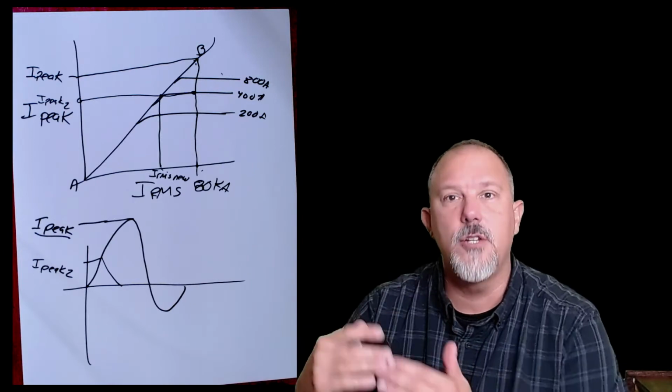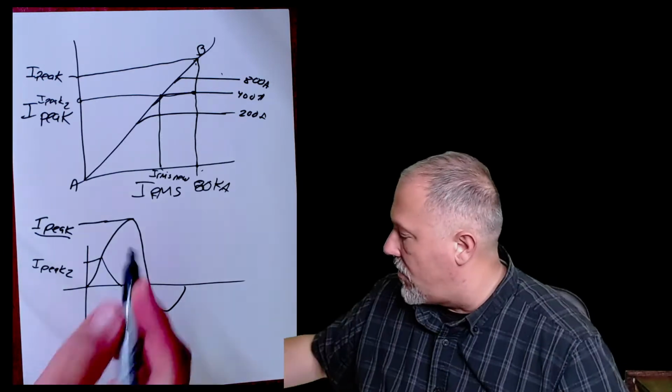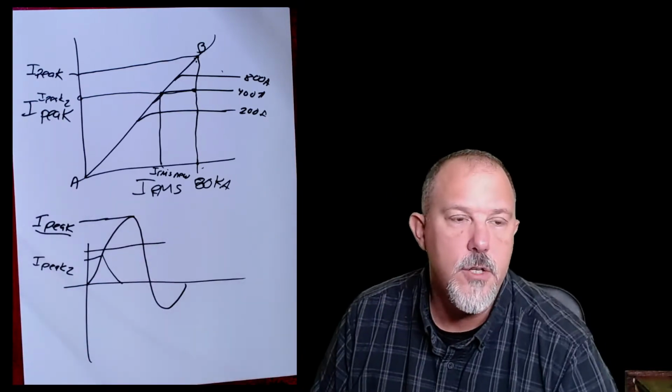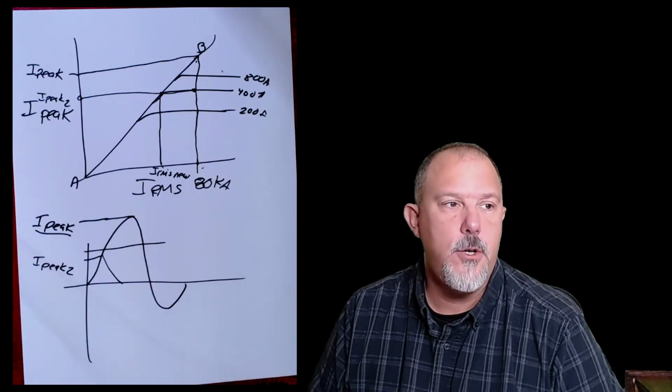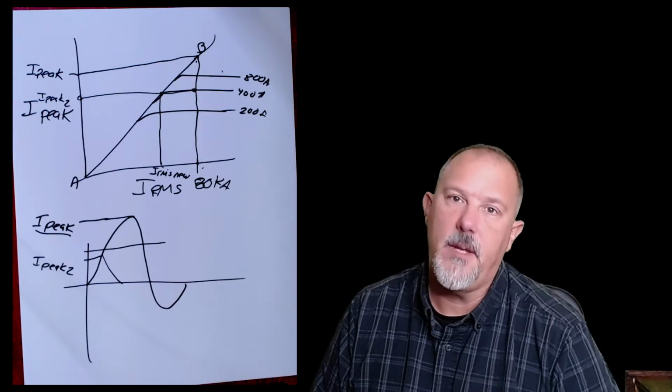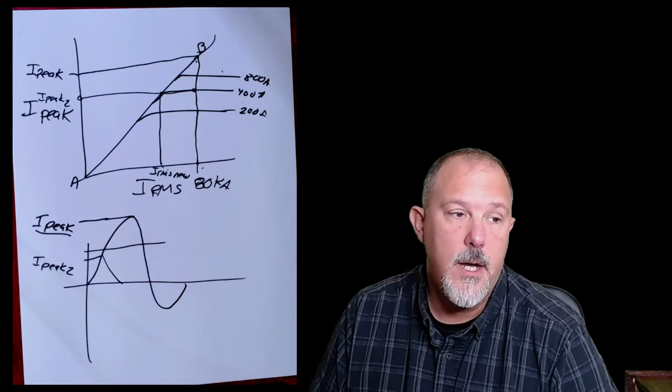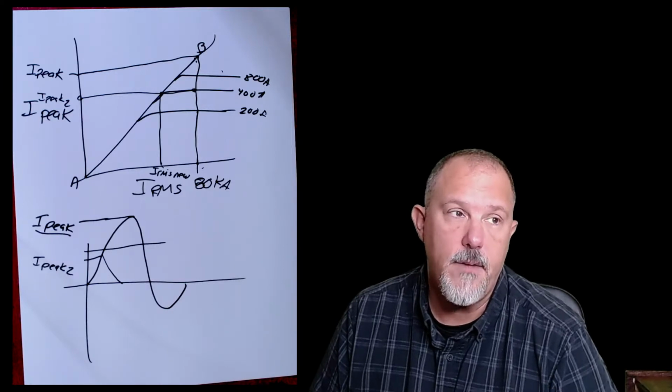So we'll go up and over instead of up, over, and down because if I go to the RMS, it will give you a lower number, right? Because what's RMS of this? There's my peak. My RMS is right there in the middle. So my root mean square, right? So 508A will make me use an up and over. But if I'm doing a busway thing, I can go up, over, and down as long as it's not a UL 508A application.